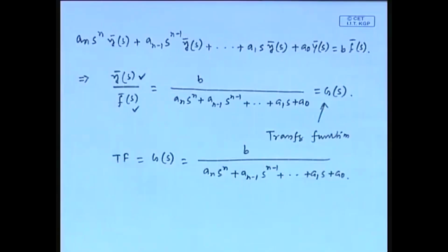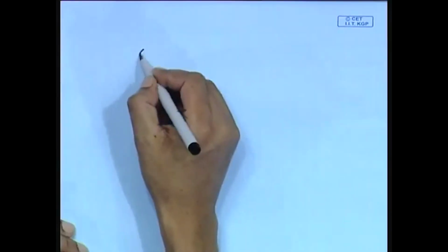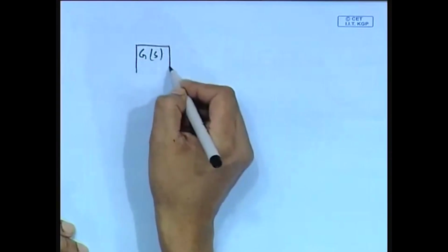You see, this is the input output model, fine. So, transfer function represents the linear or linearized input output model in S domain, Laplace domain. So, we have represented the process in time domain using the block. Now, we need to represent the whole process in terms of Laplace domain. How we can represent it? It is very simple. We will represent the process by G(s) here.